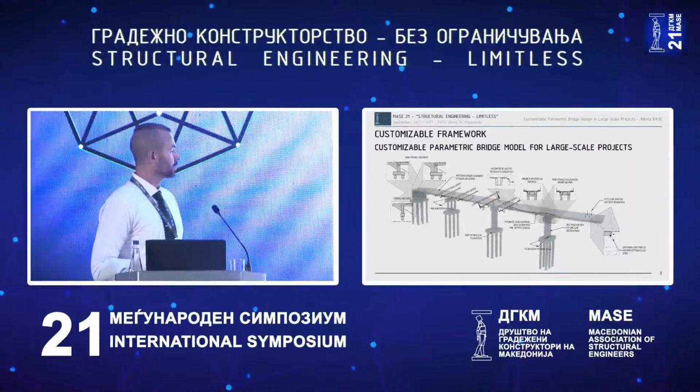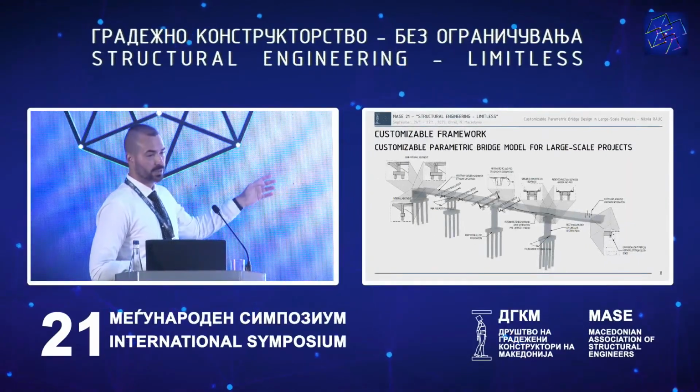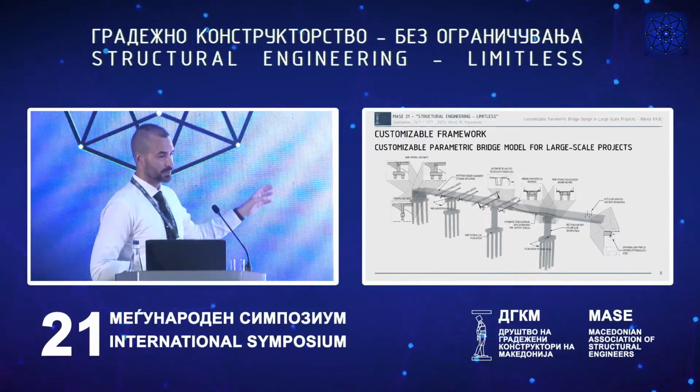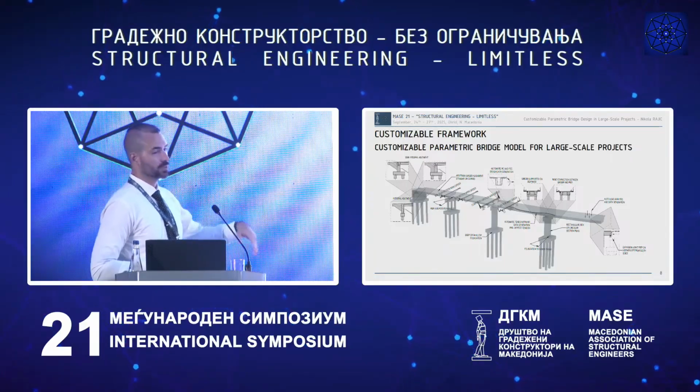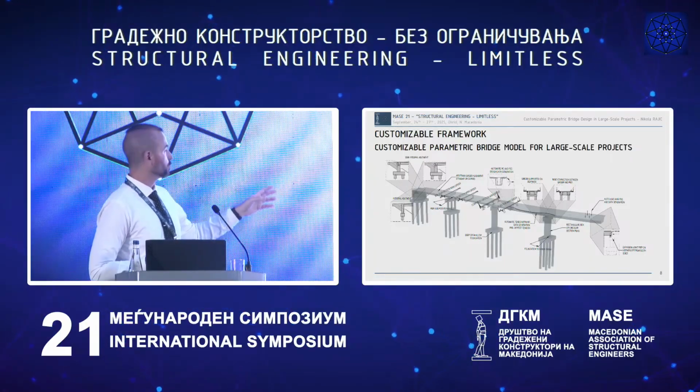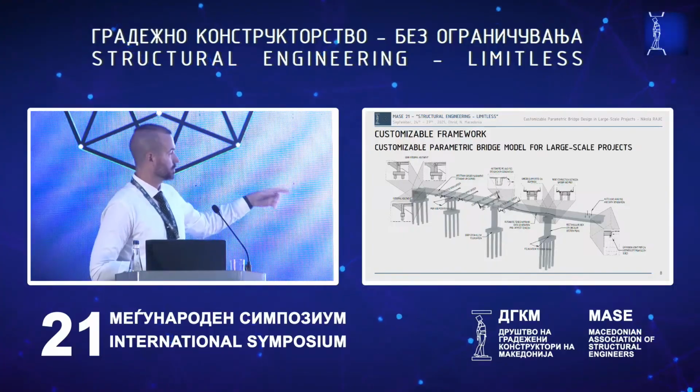Also, important thing is that this parametric model does automatically load analysis. It applies all loads, generates all load combinations. It also adds automatically tendons, strands.